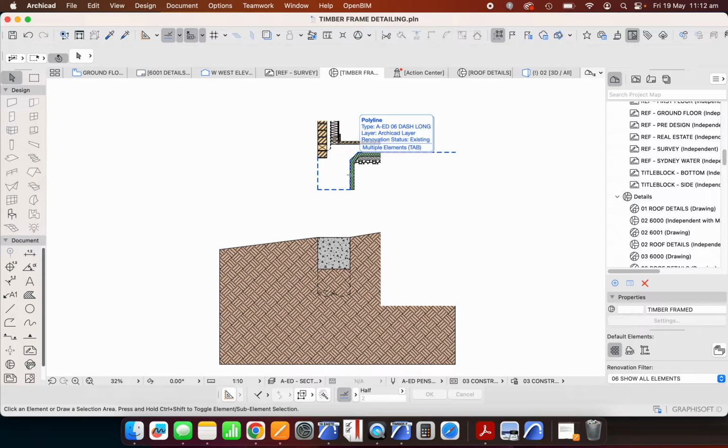All right, next, we have a brick pier that's not a continuation of the wall. Another way of saying that, it's not continuous. It's an engaged pier that we're going to see in elevation, but we're not going to be seeing in section. And so that's a brick. So we'll start with a brick and we'll represent where this goes. And so it's the same height as this brick in section. And in this case, it's a full length. So it's 230 millimeters long, and it needs to move away 10 millimeters from here. And what we're seeing in elevation is that there'd be a mortar joint.